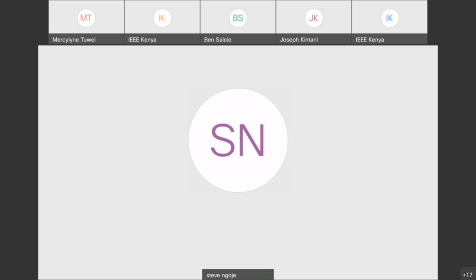If, for example, I remove one panel, that means I'll not be able to achieve my energy target within the 4 hours that initially I'd used to design. But if I add one, it just means that I'll get it within probably a shorter time, with a fraction of a few minutes. So there's that. The problem is, don't over increase it, because then the cost becomes excessive, but also don't undersize it such that it does not really help you.